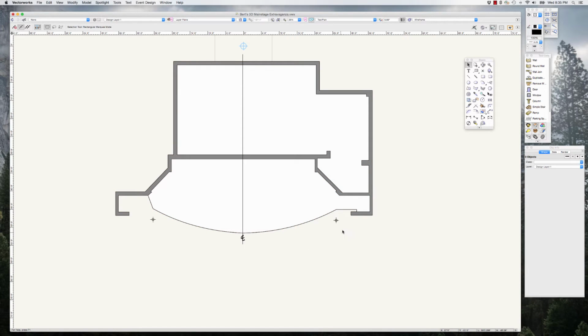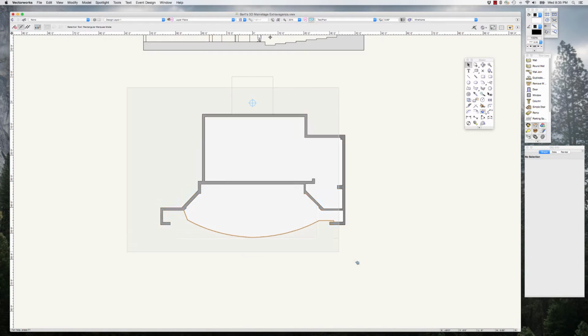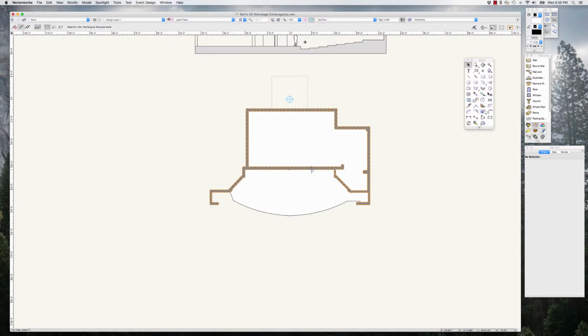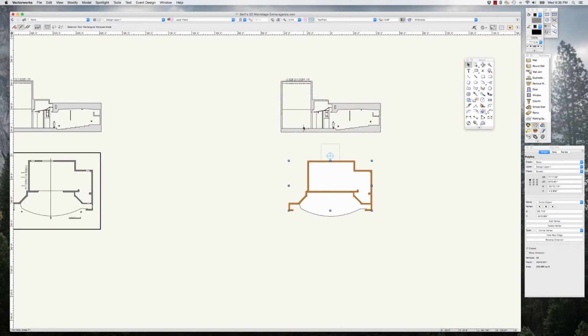So I'm just going to declutter and get rid of all this extra stuff, including the center line, the mystery line, the other mystery line. Okay, hopefully there are no more mystery lines. There should only be a couple of, oh, so there's still lines left here that were the original lines. So there should only be two objects here if I select. Okay, good. There's the walls and the floor. So what I'm going to do now is extrude. I'm going to select the walls and extrude them the 40 feet that we talked about measuring from the top of the stage deck to the top of the fly loft.